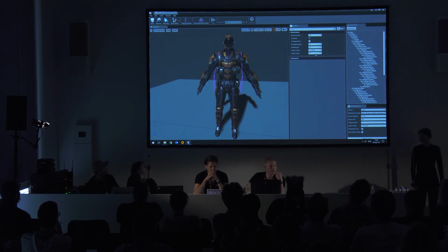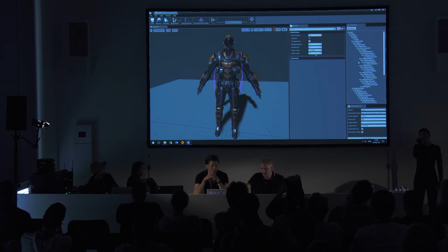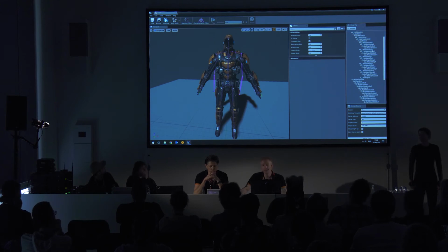They advise importing the character without MVN running, because it will then be in a T-pose. What you need to do is match this skeleton, approximately in size and posture, to the skeleton inside the actual mesh from Epic themselves. What you can do afterwards is delete the bones that we don't use. MVN, for example, doesn't use the fingers. It's just to clean it up a little bit. I don't think it's really necessary, but it's something you can do.